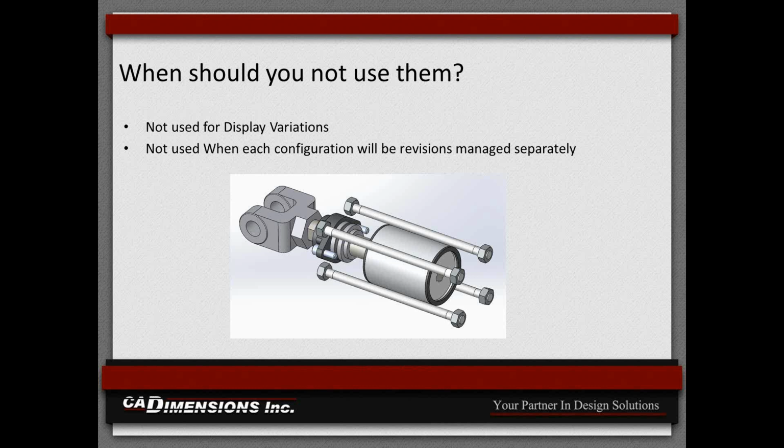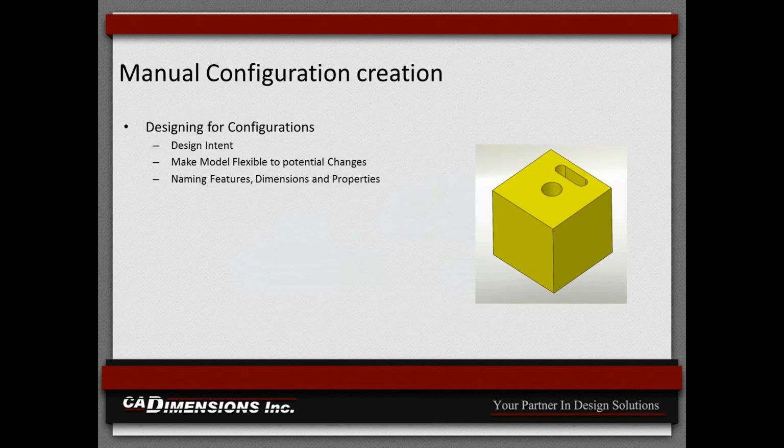It's kind of configurations for how your models look, hidden line visible, hidden remove, the color, the transparency, the hide or show. You never want to get into using configurations for display. There is a way to tie display states to configurations, but I think that's a separate conversation. So these are two reasons why I wouldn't use configurations in some situations.